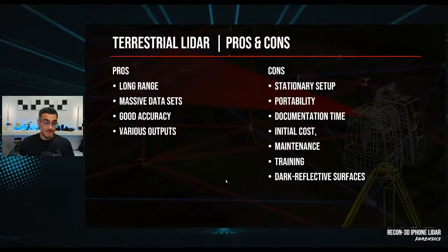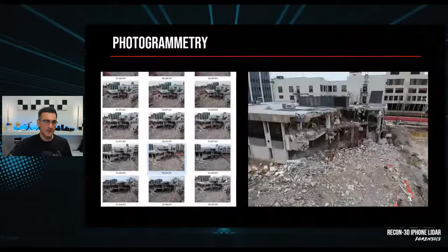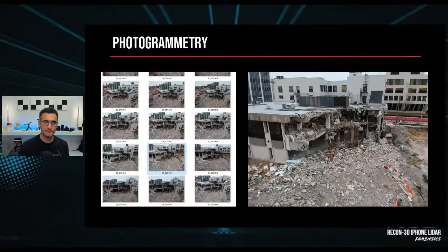The other one is that there are some things that the scanner just doesn't do. So glass, very black, dark surfaces. A lot of scanners these days actually do a pretty good job of it, but you'll find that you get more noise, you get more errors. Reflective surfaces can cause a problem. You get a lot of streaking, a lot of, I'll call them artifacts for lack of a better word. So a number of things here to consider when we talk about the laser scanner.